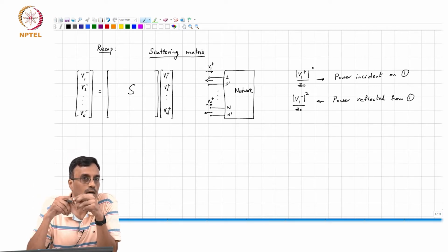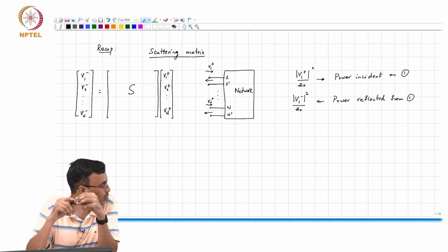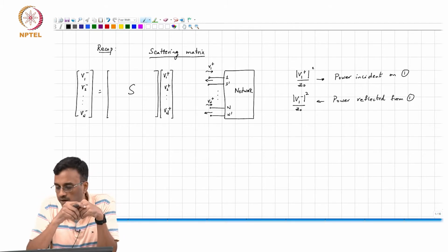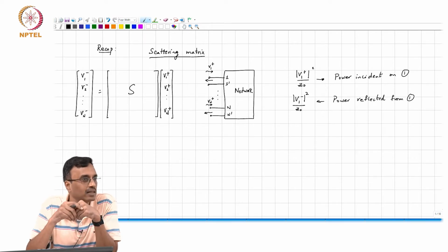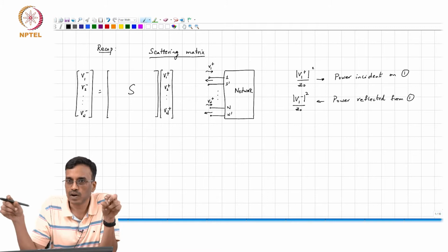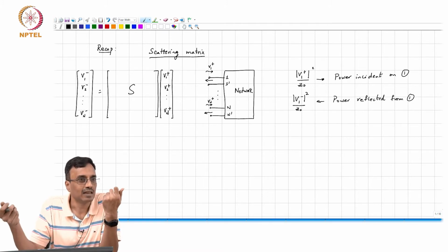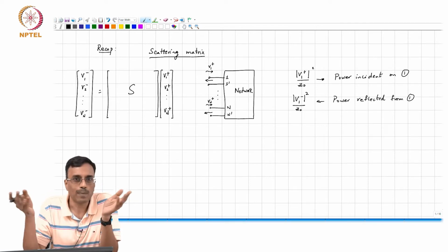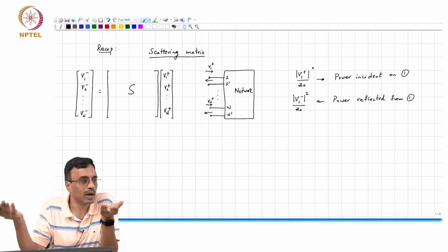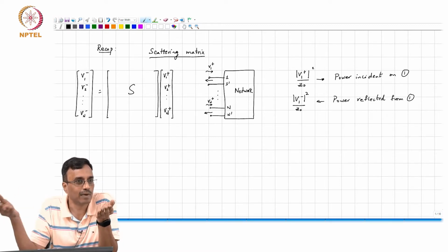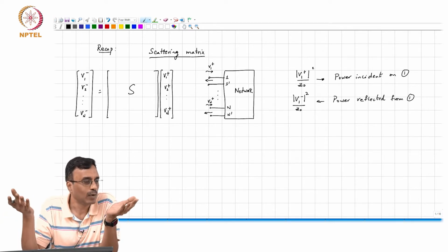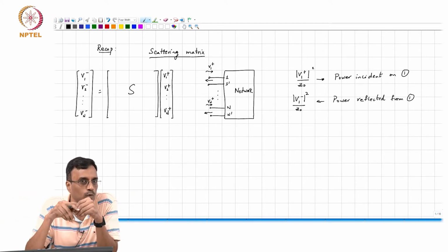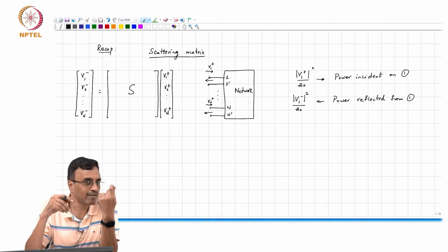What if our line impedance and the terminating impedance are not both Z0? Of course, now he brings up an interesting point. He says, this is all great in theory, where the characteristic impedance of the line is exactly the same as the terminating impedance. In reality you will never be able to make them exactly the same, so what do you think will happen? Well, we can do the math, but what would you expect? It will become dependent, but what comment can we make about that dependence?